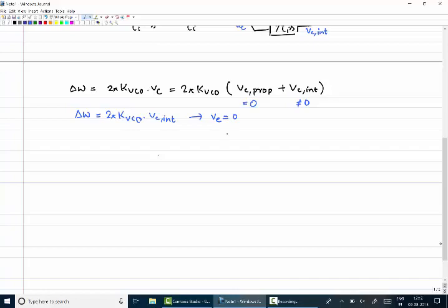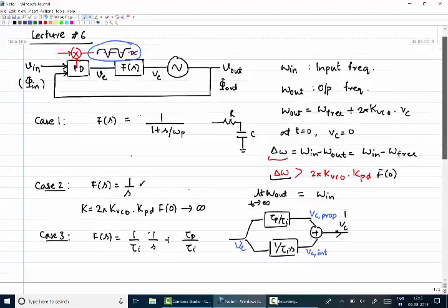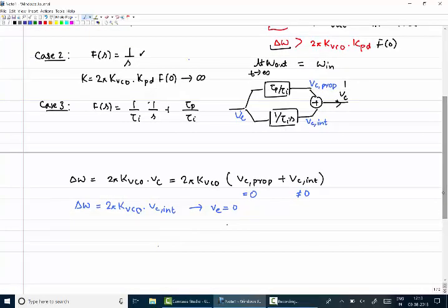No, that is not the pull-in voltage as such. The pull-in voltage, the way we defined it, was for when you started with this PLL at time instant t equals 0, there will be a certain error at the output, right? The feedback has not yet kicked in, not that effective, the values are still low, right? So it has some DC voltage. That starting voltage at that given instant of time is the pull-in voltage. It does not have much importance, because this voltage keeps on changing depending on the frequency error.